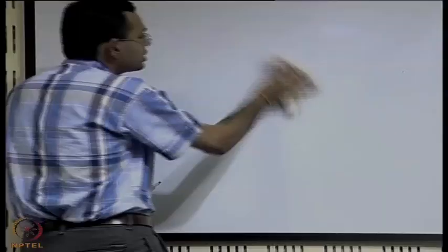So, till now we have loosely talked about fluid, we have not seriously defined what a fluid is. Now, common sense wise, if we are asked what a fluid is, obviously we will say something that flows is a fluid, right. And loosely speaking, this is not a bad definition, but there are many things which flow, but those are not so-called classical fluids, those may be in a borderline between fluids and solids, so to say. A very formal definition of fluids is like this, that fluids are substances which undergo continuous deformation even under the action of very small shear force.